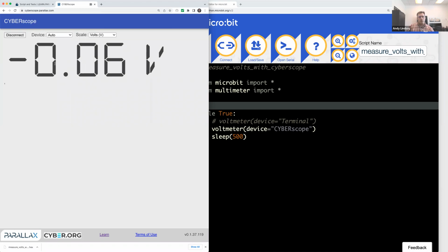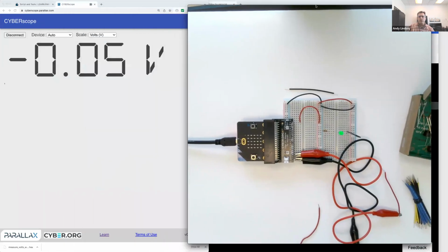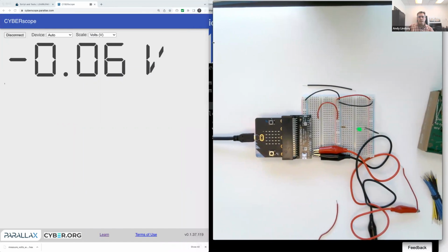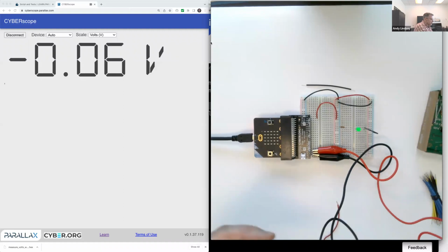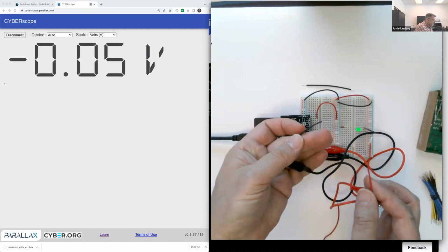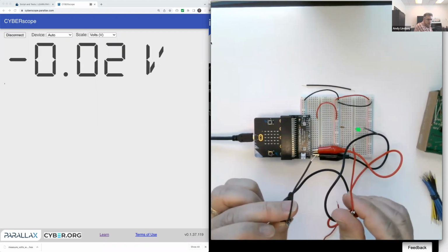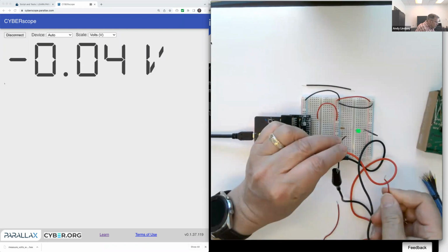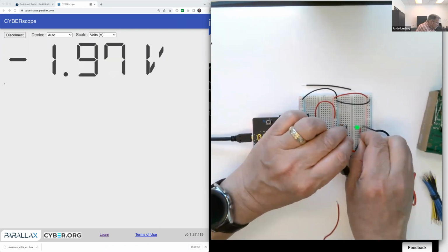And what it will show you is a voltage measurement. Now, once you've got that voltage measurement going, you can use the same probes that we used to measure the continuity, and you can put them next to opposite legs in the light to measure the voltage across the light.